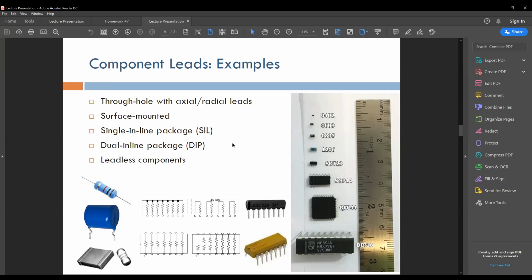So for example, if somebody came up with 0603 and somebody came up with 0402, they would both be okay. I just want to make sure that you understand the meaning of the word footprint and that you actually made an effort to find a component with a very small size. If you come up with something like this, for example, diff 18, it doesn't make sense.